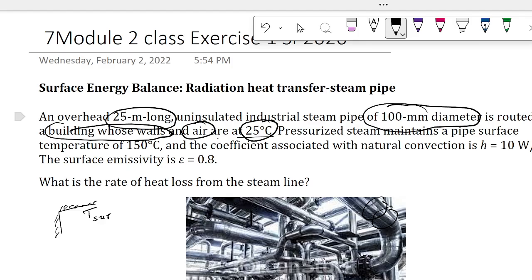We're going to write the givens, find assumptions, the engineering format, right? And then when we solve the problem, we'll do the surface energy balance, right? On the surface. So that's what we've done in the homework, right? So we have conduction equal to convection plus radiation, something similar that we'll be using. Does it make sense? Any question with the strategy or approach of the problem? Everyone understand the problem? Very good? So the heat that is coming in must go out.